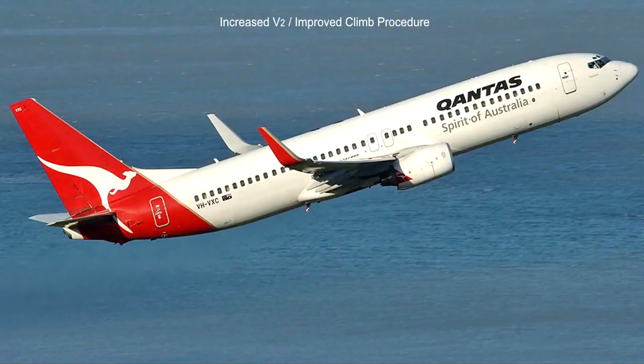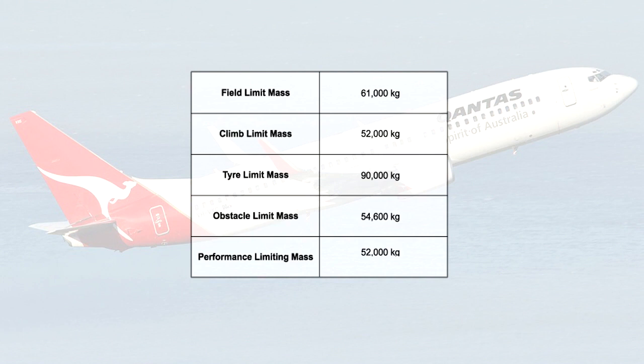The second type of additional takeoff procedure is called the Increased V2 or Improved Climb Procedure. This particular procedure is used when the performance limiting mass is the climb limit mass. In other words, the climb performance is poor and is severely restricting the potential mass of the aeroplane.